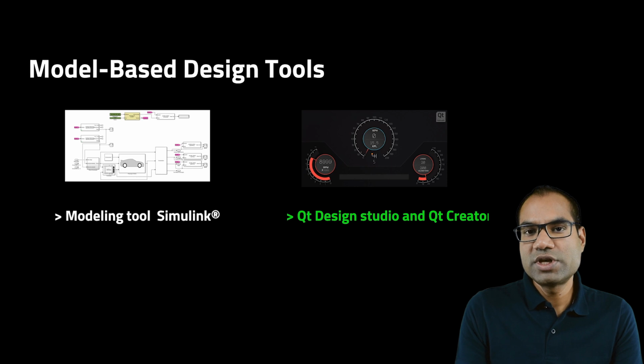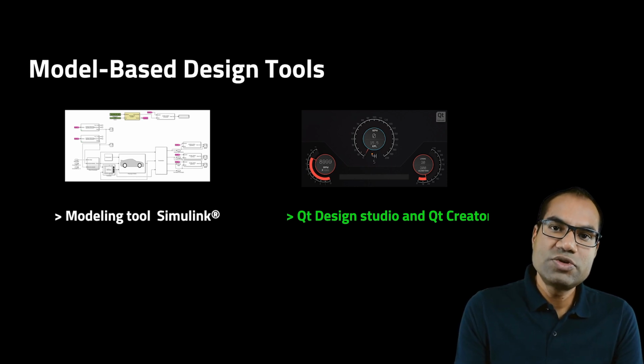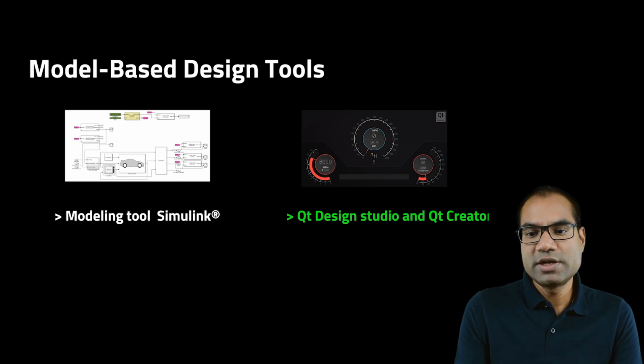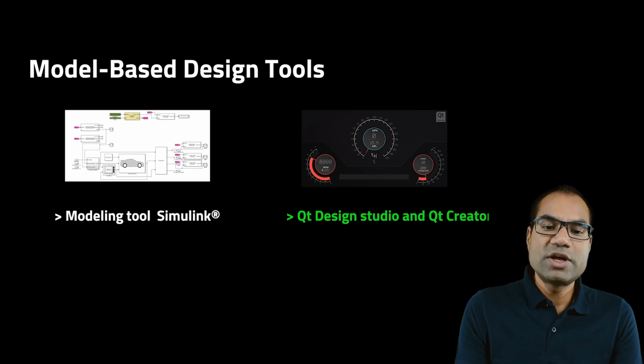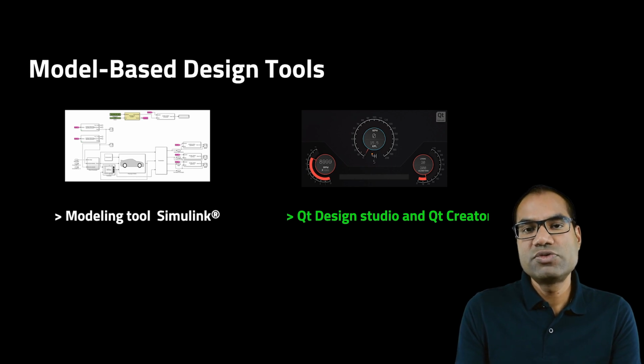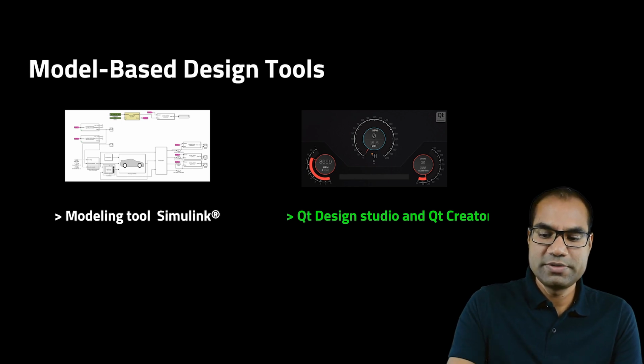It allows you to create UI very fast, and later you can use Qt Creator to compile those UIs and deploy them on the target hardware. So during today's session, I will use Simulink for the models, and for the HMI development, I will use Qt Design Studio and Qt Creator.